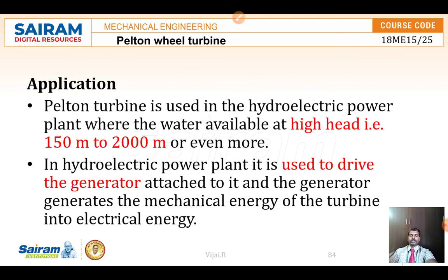As for application, it is used in high head turbines, that is, 150 to 2000 meters height, and it is used to drive the generator which is attached to the turbine. The main concept of the turbine is to convert the energy of the water into rotary energy, and that rotary shaft is connected to the generator, where the generator produces electricity, right?